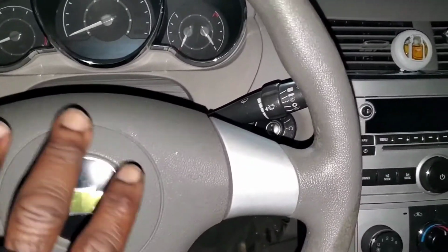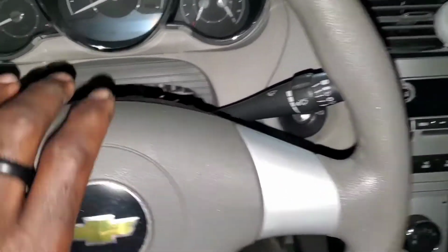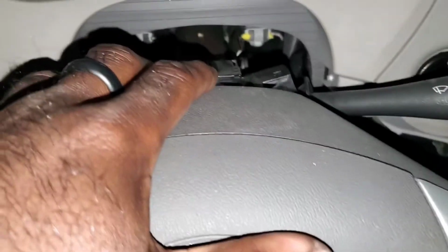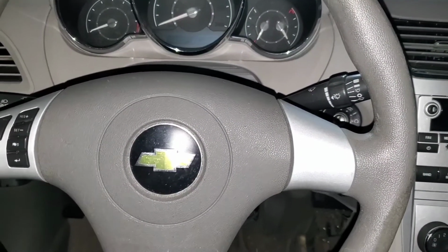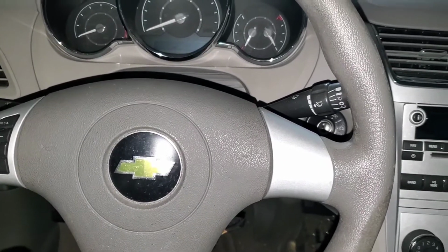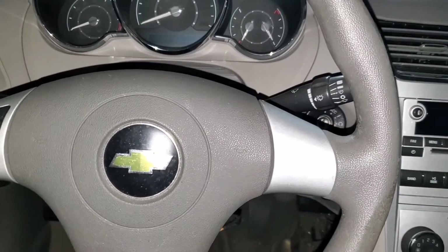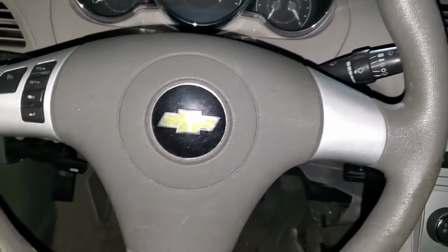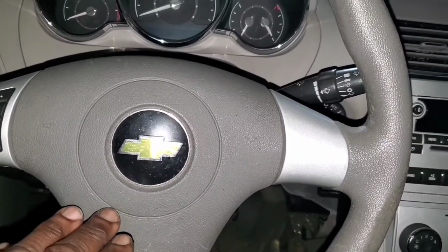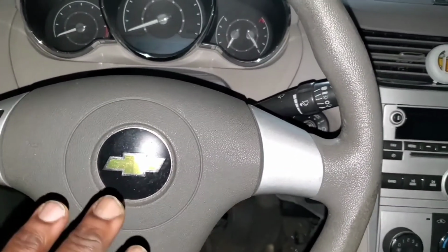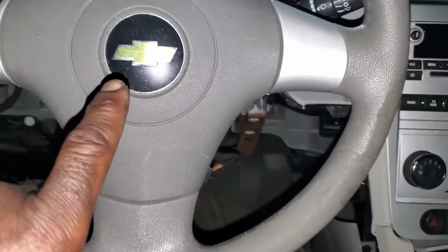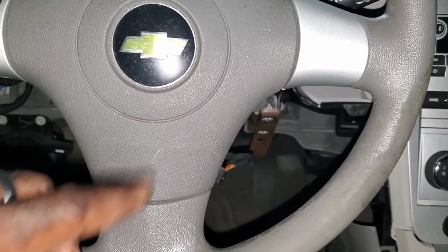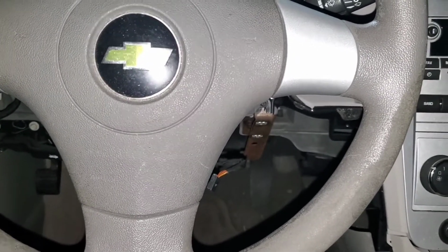When you do that, do not turn this, because you're taking the cable reel, clock spring, whatever you want to call it, right back in there, and it's indexed with only a finite number of turns left. These turns are more than the lock-to-lock number of turns, so you don't risk damaging it in normal operation. But once you remove the constraint of the rack, you could easily damage that, and that's not something I feel like replacing anyway.